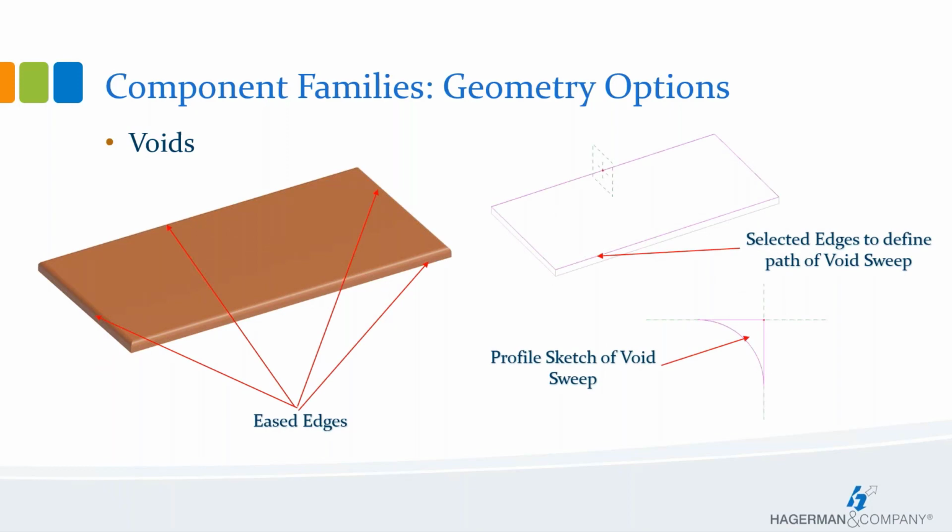And now let's talk a little bit about voids. Those, like I said, are the most common and practically used solid modeling tools in the family editor. But from there, we can add in voids for each of the tools that we already looked at. So that's what I was saying. For every solid modeling option, there's a void counterpart. So this really makes it possible to do all sorts of creations.